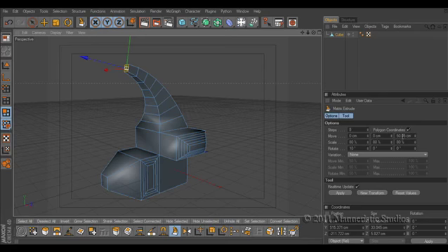We're moving up to 50 centimeters up in the air, so it's going to go up to a measurement of 50 centimeters. This is the face that we're selecting onto. Now also something else happens. We have a rotation of 10, so you see now we're going into, in the x-axis, a kind of a curve, a rotation of 10 here is going up. And we have the scale that's going up each increment at 80%.